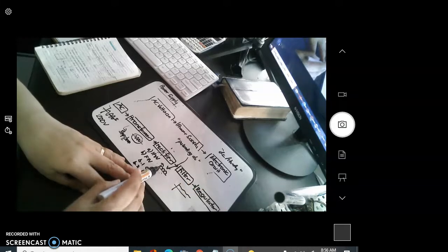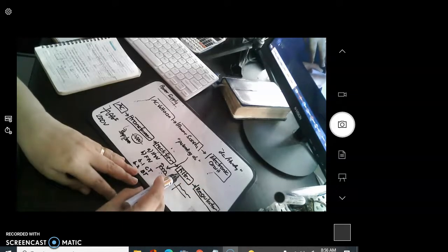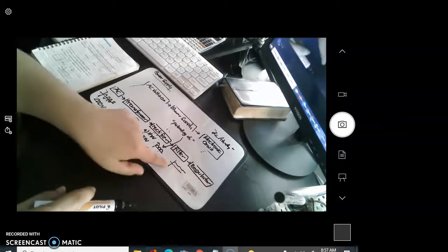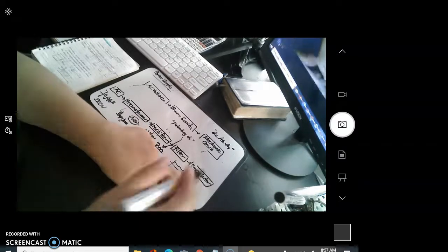So the filter circuit will improve this pulsating DC and will produce this output. From a pulsating DC, after applying the filter, the output voltage will be smoothened by this circuit. For this circuit, the responsible component to smoothen or almost flatten the signal is the capacitor. But then again, this is not the target voltage. The target voltage is a direct flat voltage. So this signal must pass through a regulator. Once this signal passes through the regulator, the output will be like this.